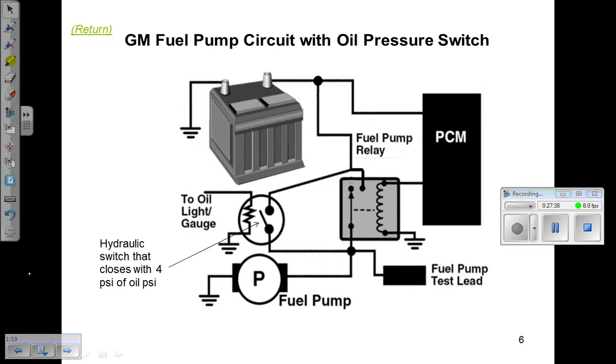Actually, real quick case study I did, low fuel pressure on a car. 9 times out of 10, low fuel pressure, you're putting a pump in it. But always do your checks. And this was a former student's car, and I needed to be 100%. When I checked the pump ground, I had 6 volts on the pump ground. What happened is this vehicle was in an accident, had some body work, and the bolt that holds the fuel pump ground to the inside trunk area was loose. All that car needed was the bolt tightened up. This student was very happy with me for handling that for him because it didn't cost him any money to have a fuel pump put in it. So be careful. Again, loaded circuit, voltage drop testing is the key.